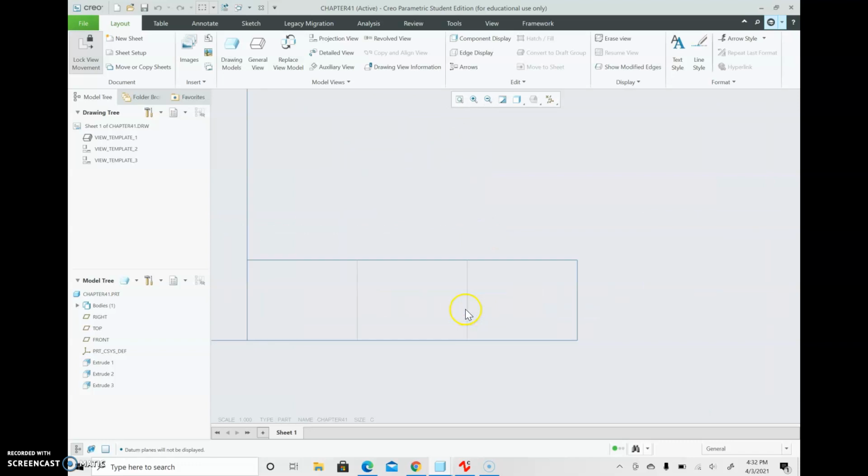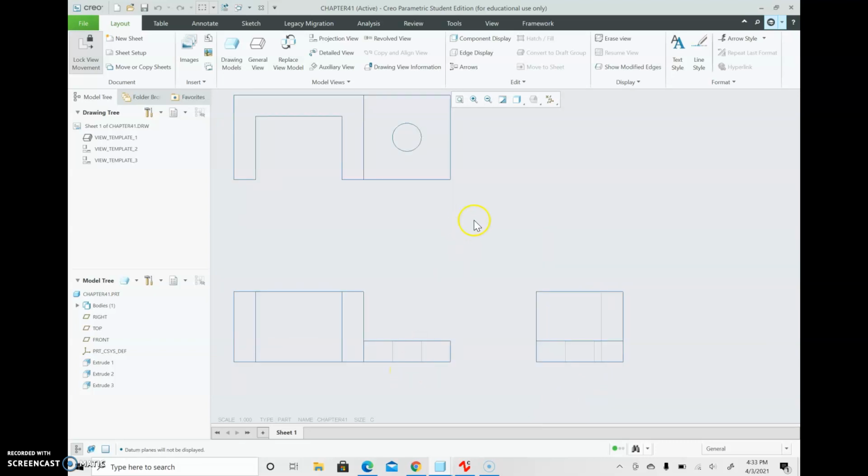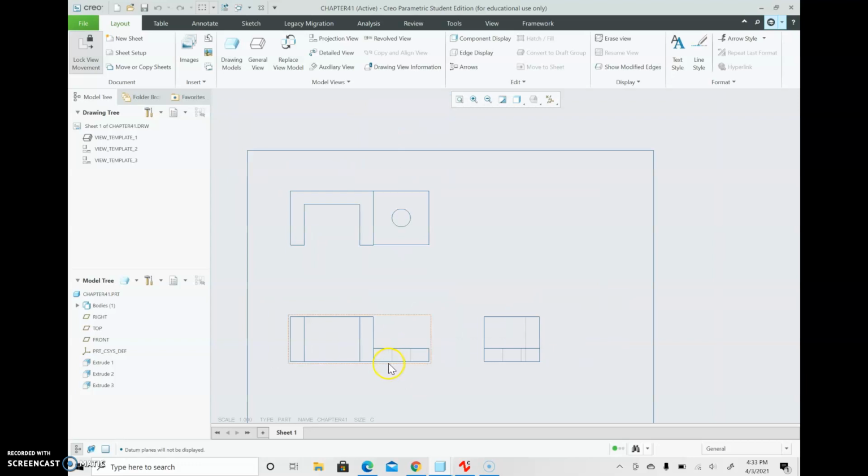And look here. If you look at these two lines, they look different from what's around them because they are hidden lines. Remember, the hidden lines are lines that you can't see because they would be behind your object. These two hidden lines indicate that this circle goes through your object. So let's add some dimensions to it.